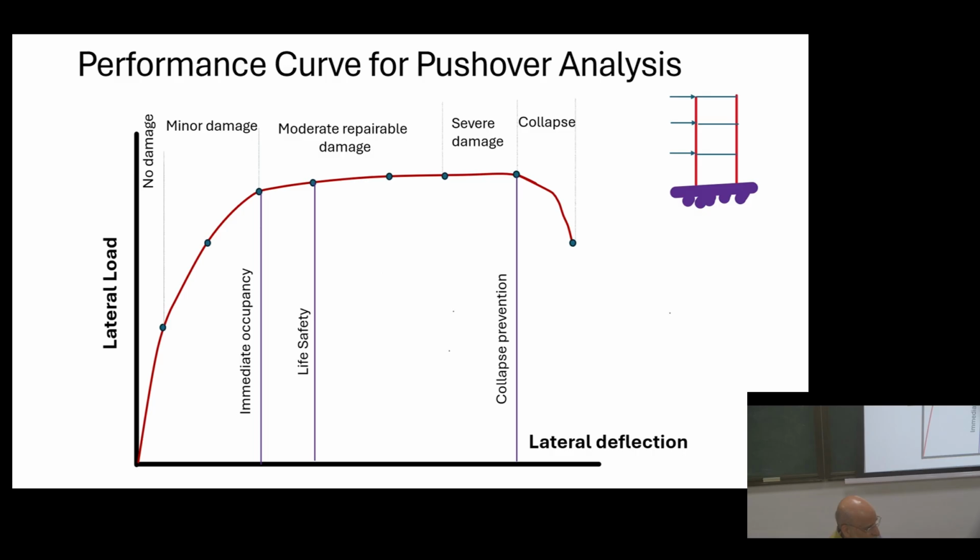As a train moves, a lot of vibration is generated, of different frequencies. Those vibrations should not transfer to the top, because at the top you are going to have a restaurant and other occupancy. So on the top of the columns, they put bearings. Those bearings provide some sort of isolation, or take care of the deformation which takes place, so it will not transmit. So you can avoid this.